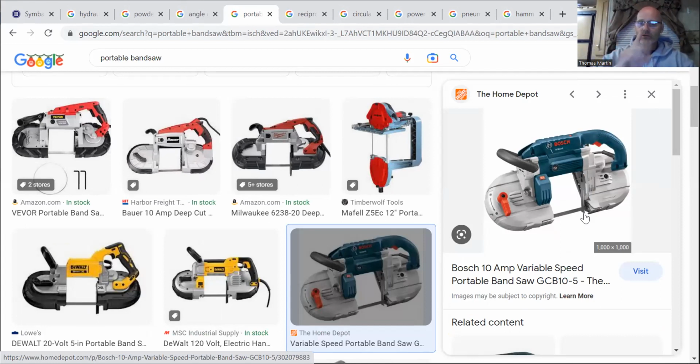So what you want to do is place your wood right there where my mouse cursor is sitting. You want to place your pipe or whatever you're cutting against that stop, because if you start it at the other side, that blade's going to pull it against you and could break the blade. It could cause you to hurt yourself, drop the saw. It could create a lot of situations. You always want to start with the material against the stop. That goes with all tools. Any drill, any saw, everything.